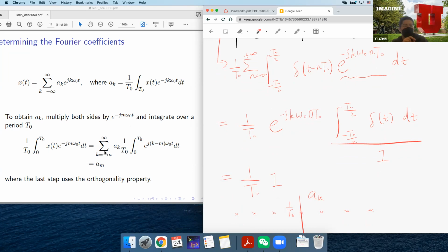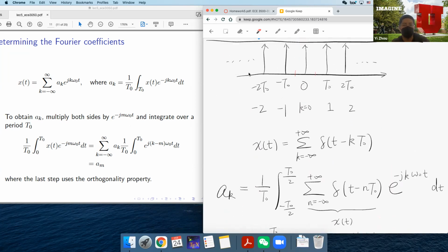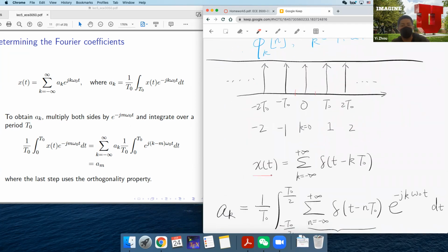First of all, to answer the first question, is this a discrete case? No, we are looking at a continuous time signal. We have x(t) as a continuous time signal, because the impulse signal delta(t), where t is a continuous time variable, is a continuous time signal. We are summing up infinitely many impulses, which are periodically located over the time interval. So x(t) is a continuous time signal. It looks like discrete, but here t is continuous time. Remember that it is not x[n].